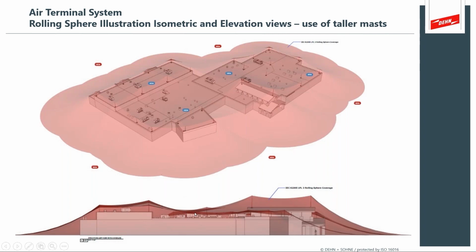And what you see in an illustration like this is that all of this equipment, these chillers and condensers on the top of a building, maybe it's a radio, maybe it's something else associated with a very sensitive asset. Well, those objects on the top of that structure can be protected from the lightning direct strike because the electric field sees the air terminal first, and it has a stronger effect to the electric field.